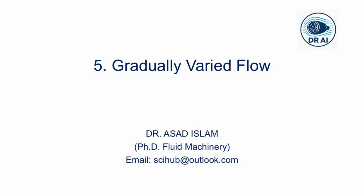We will use the concepts we have built in this lecture, the Manning's equation and the force balance, to analyze how water surfaces rise and fall as they move downstream. We will also classify the different types of profiles that can occur. For now, I want you to appreciate that the simple-looking Manning's equation is one of the most powerful and widely used tools in civil and environmental engineering. It is the key to designing the canals that irrigate our crops, the drainage ditches that protect our roads, and the sewers that serve our cities.